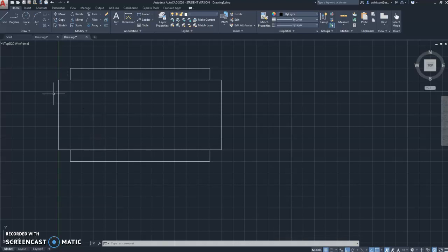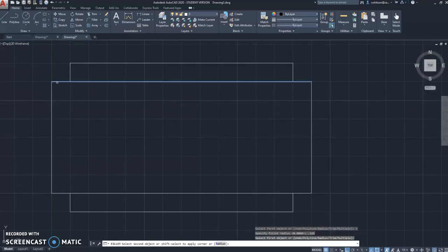Now, these outside corners need to have a fillet. So I'm looking at the drawing to see there's a general note down at the bottom. Note fillets and rounds 1/8 radius except as noted. And there's nothing here indicating that they are otherwise, so that means they must be the standard 1/8. So radius 0.125 is 1/8 of an inch. So I can round off this corner. And I'm just hitting the space bar to repeat the previous command.